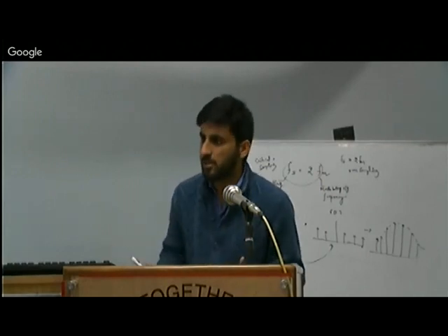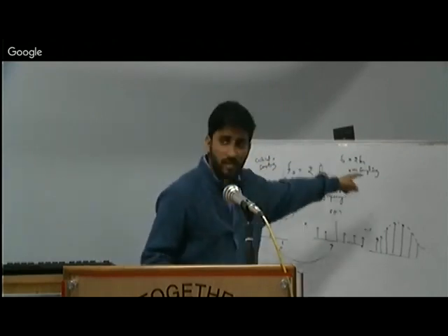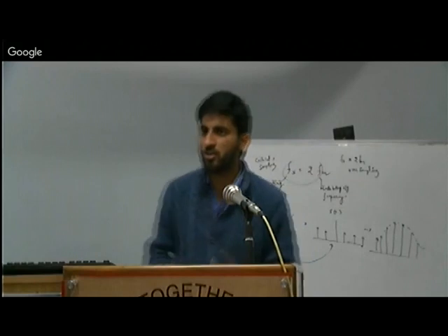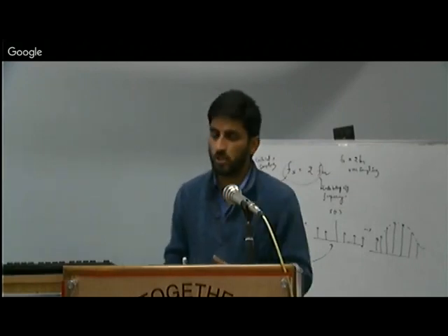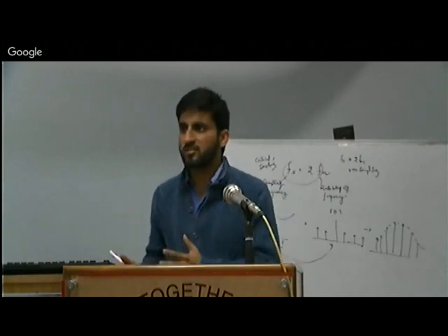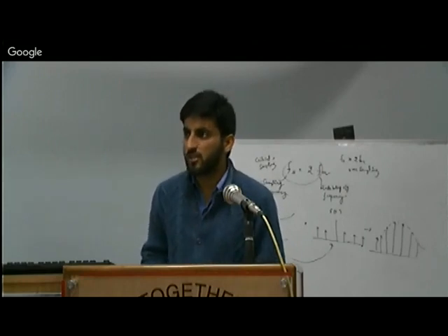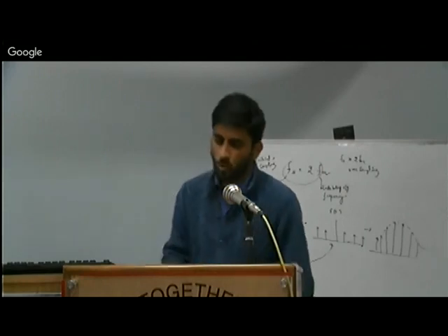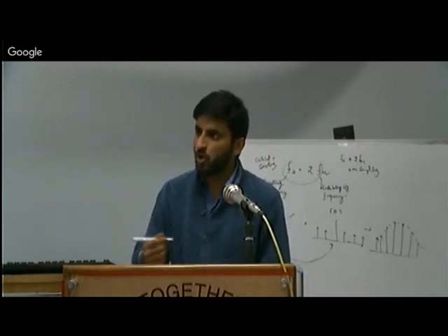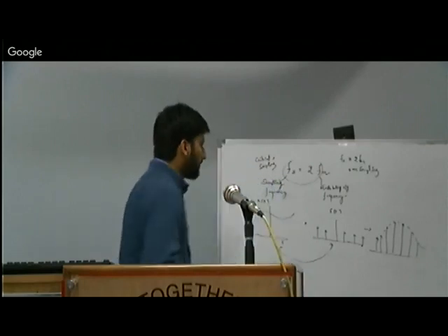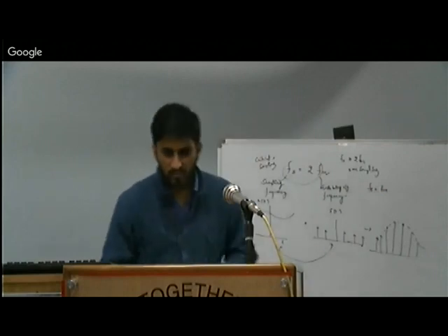and we also need more bandwidth in order to store such a huge amount of samples. I mean, in order to reconstruct my original signal, I need almost double the samples of the samples which I took in the starting. So in order to avoid this, so that we are able to generate my original signal even with Fs equals to Fm, the concept of compressive sensing comes into the picture.